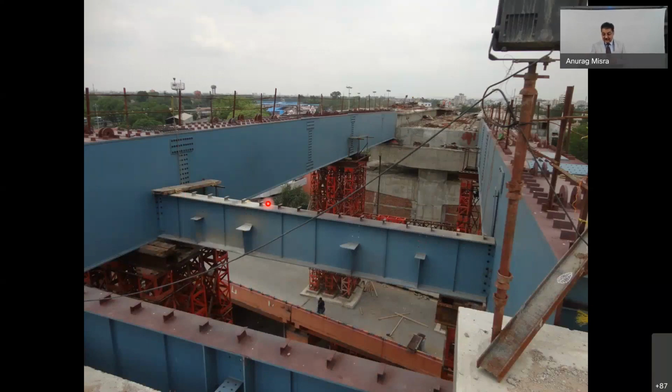So this whole thing is planned in a way that, as I said, this is a metro station. So these cross beams, there are two main girders. They are box girders, steel box girders, prefabricated. And then there are some cross members which are joined at the bottom of this cross girder. It has been purposefully done because you need to have a platform here and the rail has to run on this level, right? So the depth of the girder is decided in a way that the whole thing comes as required.